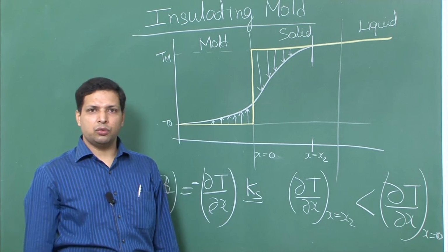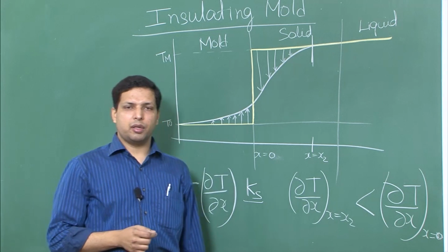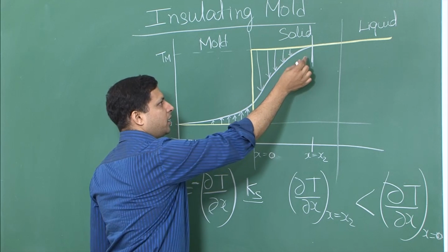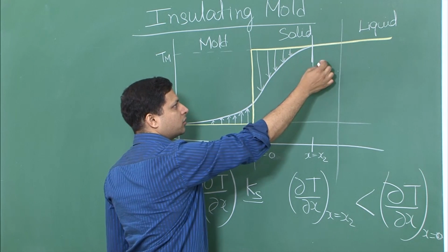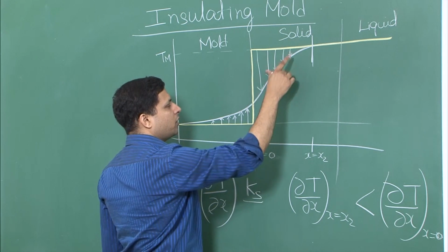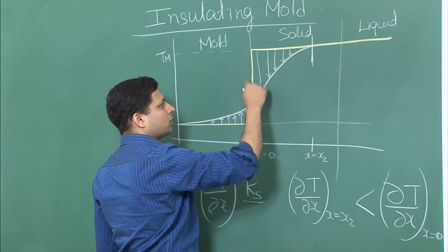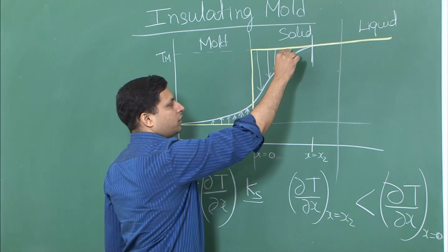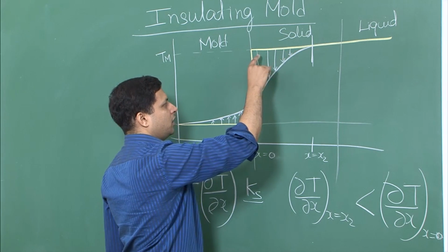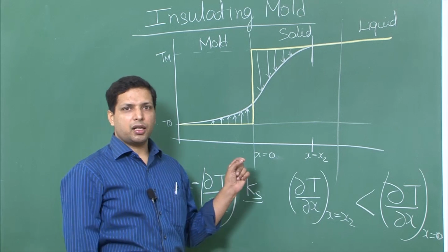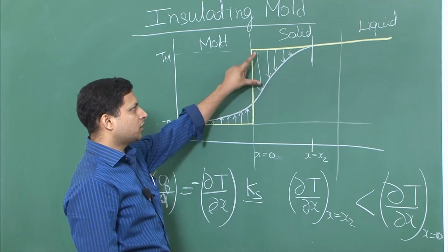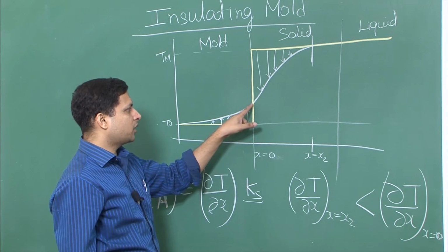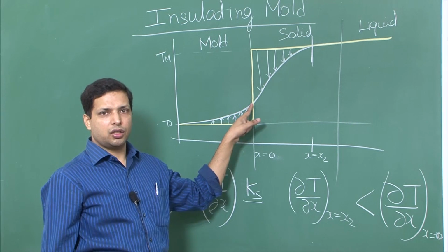When it is cooling down, an amount of energy equal to Cp delta T or Cs delta T will also get added into the heat that has gone in here. The delta T for each and every point is different, so you will calculate the Cp delta T for each small incremental amount of the solid and calculate the total additional energy. That will be equal to the total energy that is getting transmitted at this point.